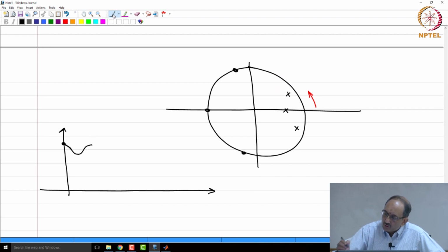Therefore, what is going to happen is the gain starts to fall, and then when I keep going along, I am now going to approach this 0. This 0 happens to be on the unit circle. Therefore, what is going to happen here is response keeps falling down, and when I am exactly on top of this 0, I hit a 0 in the frequency response.